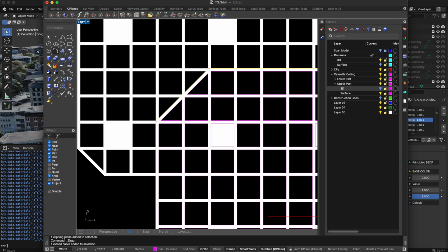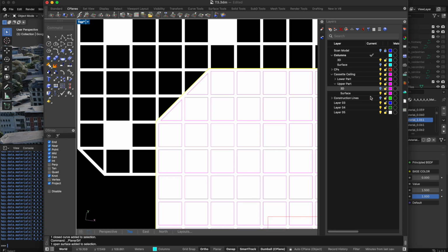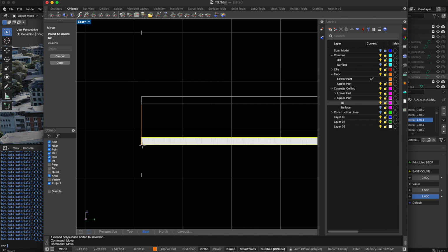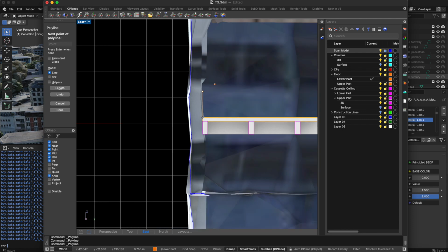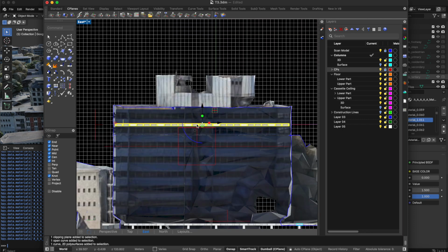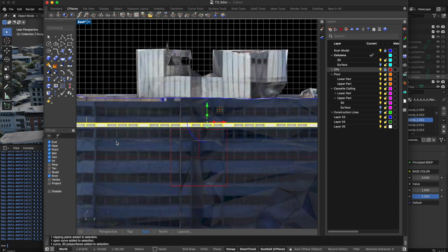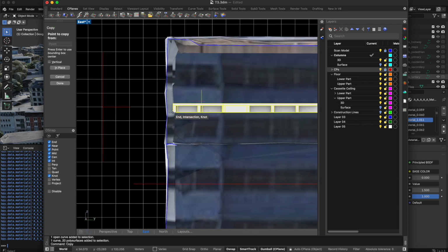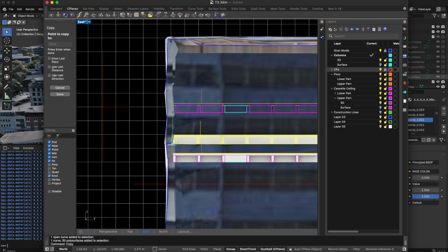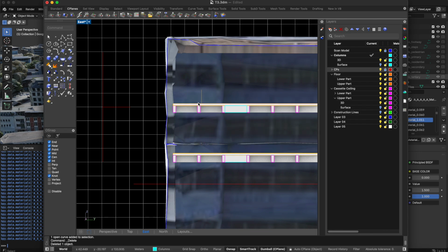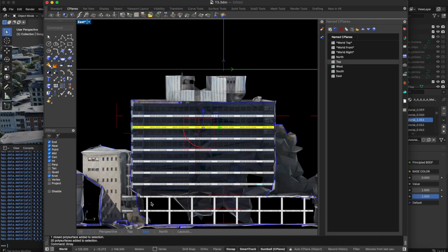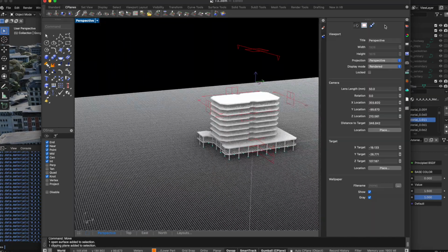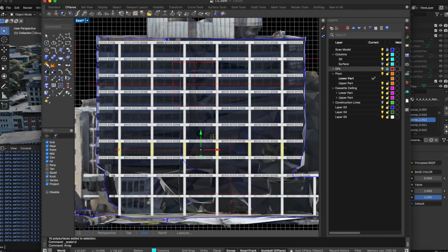To use the parapet height as an orientation, I first create a floor on the top of the covered ceiling. Then I can assume a parapet height of between 90 and 110 centimeters from the floor. I move this package up to the bottom edge of the window and set the story heights that way. I copy it to the next window and measure the distance between the floors. Then I round the number up or down and array the others. I select the columns with their support elements and array them in Z direction.